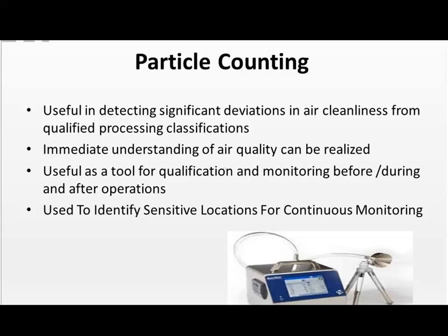You want to know what it is in a dynamic situation when there is manufacturing going on, and then you want to know what it is at the end of the day or at the end of the campaign when the manufacturing has stopped. It gives you a good idea of the types of particles that are being generated, the recovery ability of the test filters to recover the air, and also just gives you good information for trending.